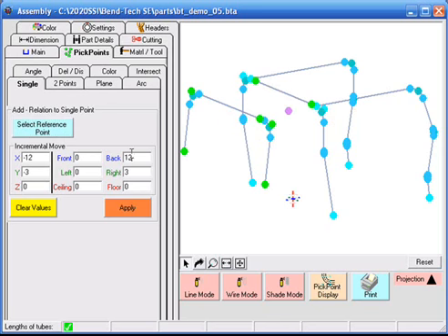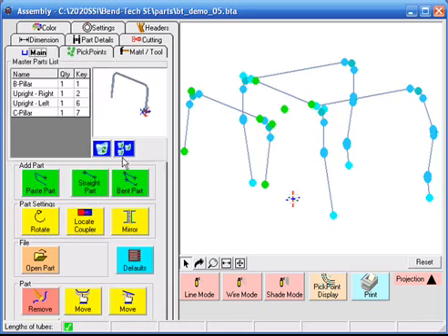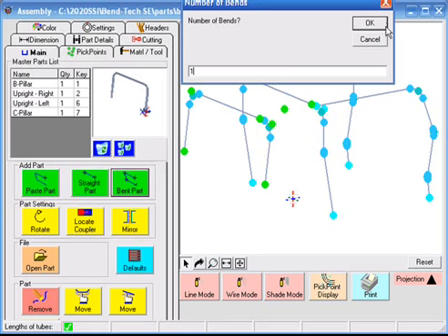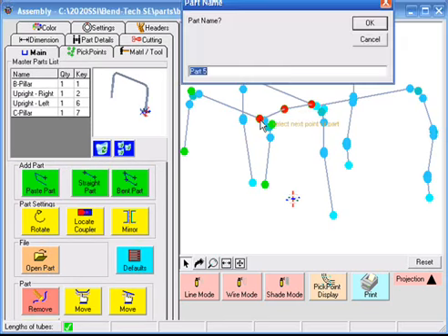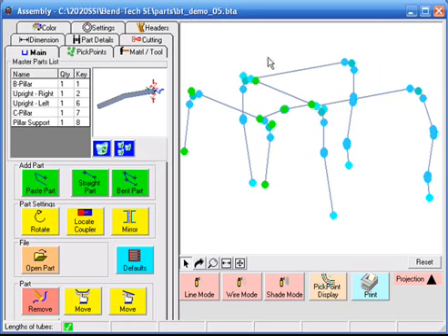Our bend will be 12 inches back from our B-pillar. Define the pillar support by selecting the two endpoints and the bend point. We will now use the paste part function to define our second pillar support.